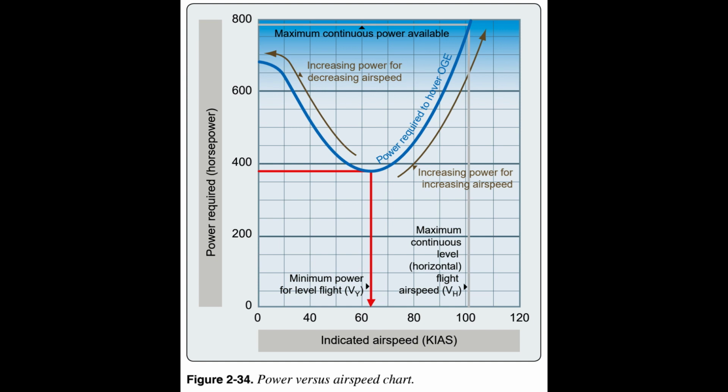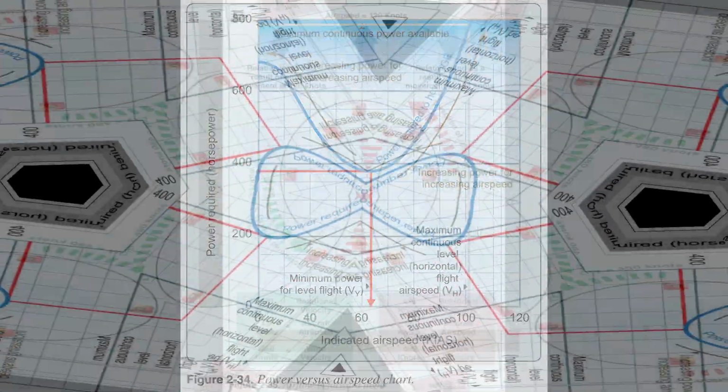The highest velocity of airflow occurs over the right side, 3 o'clock position, of the helicopter, advancing blade in a rotor disc that turns counterclockwise, and decreases to rotational velocity over the nose. It continues to decrease until the lowest velocity of airflow occurs over the left side, 9 o'clock position, of the helicopter, retreating blade. As the blade continues to rotate, velocity of the airflow then increases to rotational velocity over the tail. It continues to increase until the blade is back at the 3 o'clock position.